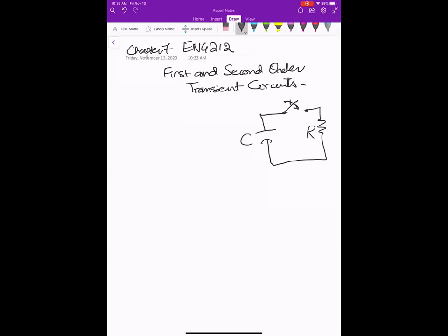So that's what we need to know, what happens in the transient state and steady state. Now let's say the voltage across the capacitor is VC(t). As soon as I connect this switch, the current flows here. And the KCL equation will become this, because it's the current that is flowing here.